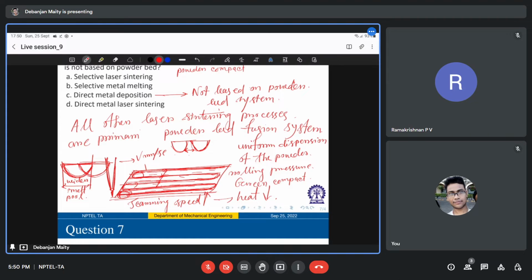structural performances. So what I was saying is, for any kind of sintering, it's not initially melted, so it's all loose powders all over, and then you start scanning through your laser, and then you melt and solidify, and then when one layer is already completed, you place the powder again over this layer, and again you scan.